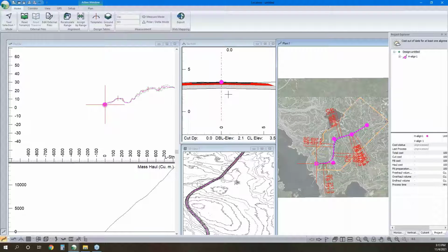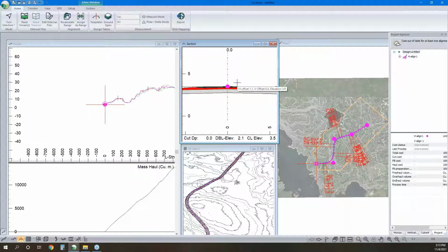Now with this, I've got my default rural road cross-section template applied. Before I do my optimization, I'm going to want to make sure that my cross-section represents the cross-section of one of my alignments. Obviously, if I'm designing a 10-meter wide road and I use a cross-section that's only 5 meters wide, that's going to create some different volumes and different interactions in the ground.